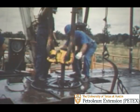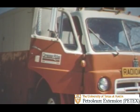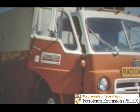At total depth, the hole is cleaned up and the crew starts coming out of the hole. We will soon learn just how well the oil mud has performed to prevent damage to the pay zone. With the drill stem out of the hole, a logging truck is called out to the well. The well is logged to determine the best part of the pay zone to complete.